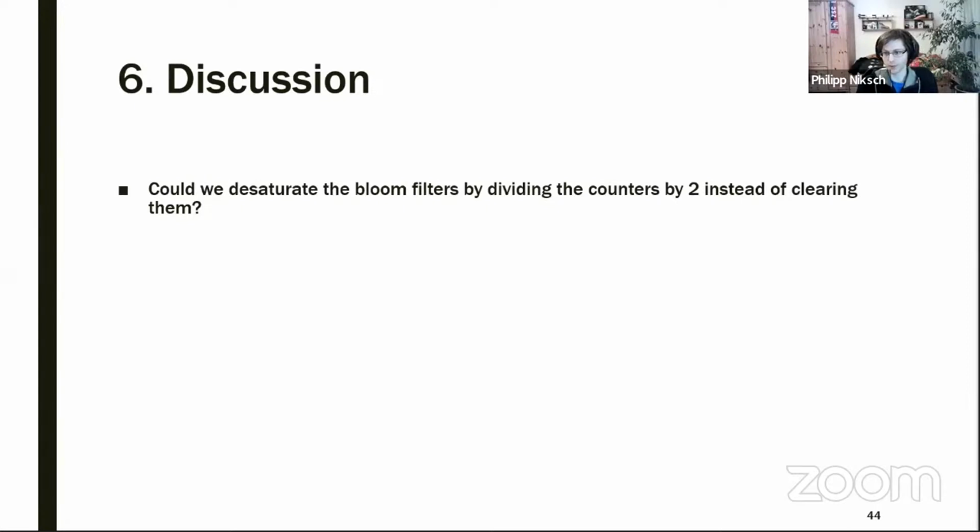Well, there's one more problem that I didn't really tell you about, because I think I just forgot to mention it. When a Bloom filter resets, the hash functions get randomized. So if a certain row has false positives for some reason, in the next cycle the false positives will most likely not be there anymore, because other hash functions are being used.